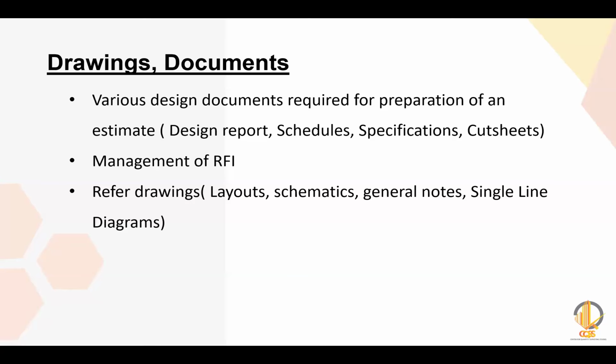What kind of information we will be receiving? Those are all the ins and outs of these things we will be discussing. What kind of schedules, what kind of specifications, cut sheets, right? Because I'm not going to train you only for preparation of BOQ. You should challenge the designer also. Provide me these details, these are missing with your design submission, right? You will have to prepare RFI by your own and send it to the designer.